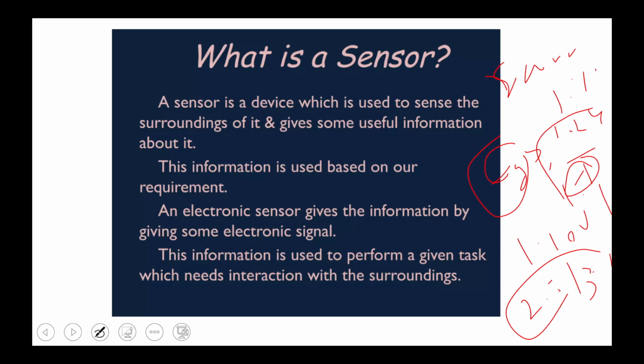If you want to use it for a particular application, you design the sensor to be selective for that particular application only. Suppose that you want to detect the H2S gas. You use it in the sewage line. Have you seen the sewage line? The sewage, the waste material. When they have the decomposer reaction, they release CO2, CO, H2, NH3. Many gases will be present in the sewage.